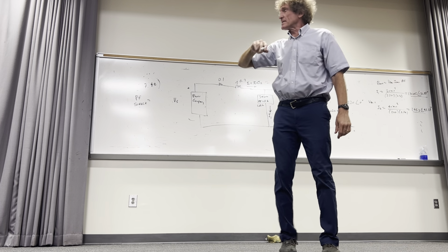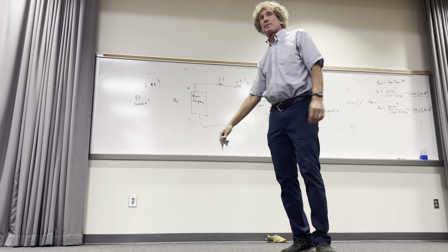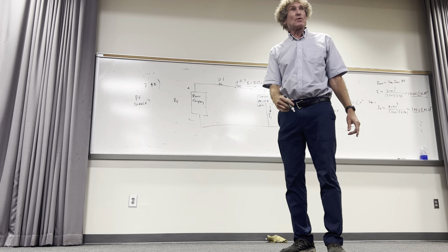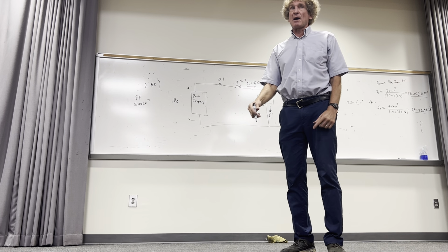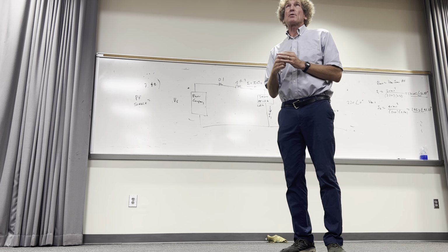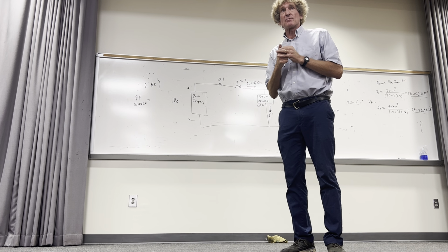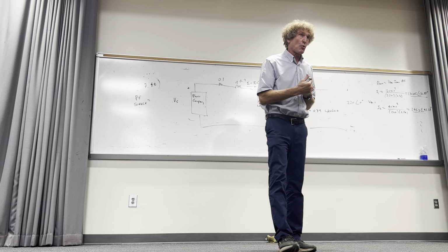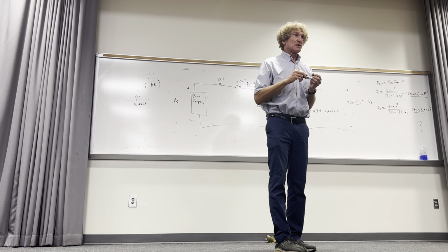All right, we need to take that current multiplied by the line impedance to get the voltage there, add that to 220. Now we got the voltage to the source, then we get the power factor. I'm going to give you problems like this. Next class period, we're going to cover complex power. As much as possible, try to be here. It's a lecture that's important here for me.